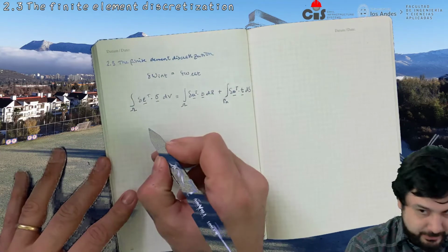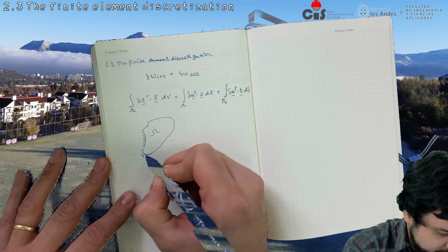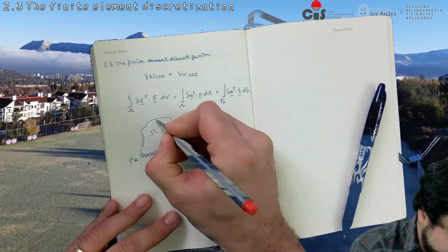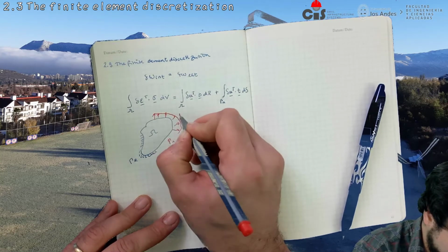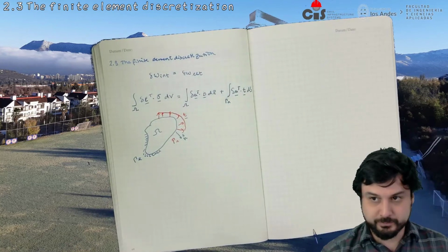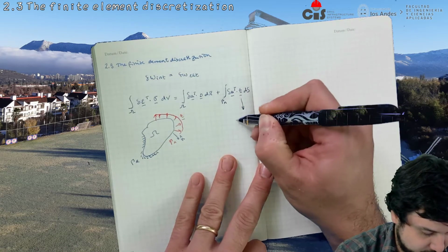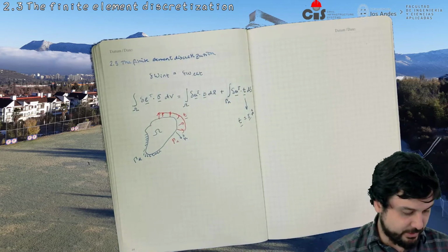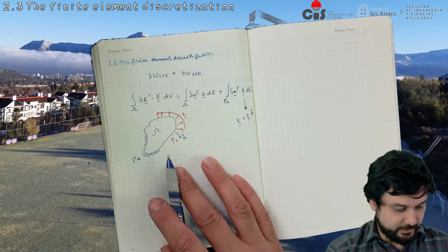And we have a domain, omega, that looks like this. It has its essential boundary, and it has a natural boundary where natural BCs are enforced. Those are tractions, and that's the outward normal. This t is equal to sigma dot the outward normal. That's the meaning it has in the equation in the end. Well, we start from this, and now we're going to discretize.